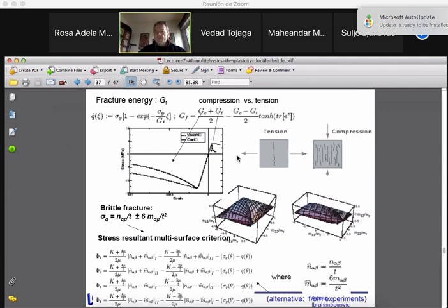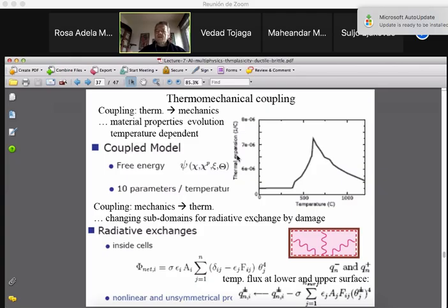In fact, for this particular model, this is the clay material, which is baked at a certain temperature, something like 800 degrees. You can see that, contrary to steel, the yield stress goes up when the temperature is increased, because you recover this kind of internal structure of the material in the temperature range where you're making it. Then at a certain point, beyond this temperature, it goes down again. So it's a very complicated dependence of the yield stress and the other mechanical material properties on temperature.